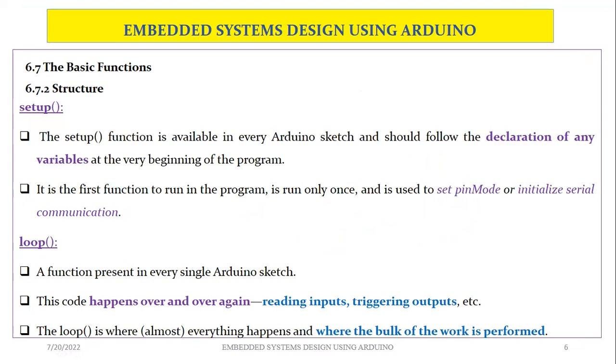So the next item is, if you look at the setup, the void setup part, like I mentioned, whatever we put there will only be executed once, and every Arduino program must have the setup part. Even if there's nothing put there, you must have the setup part as the first part of the Arduino program, usually coming immediately after we've declared the variables.